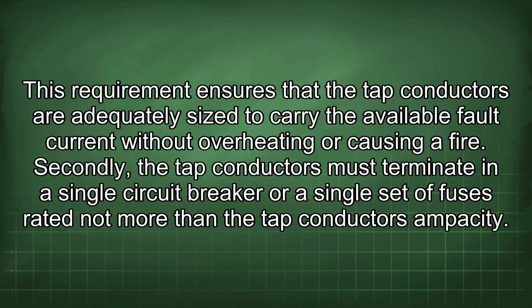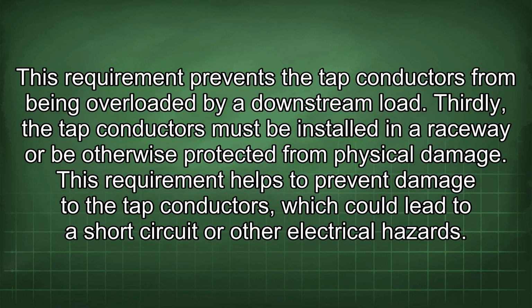This requirement ensures that the tap conductors are adequately sized to carry the available fault current without overheating or causing a fire. Secondly, the tap conductors must terminate in a single circuit breaker or a single set of fuses rated not more than the tap conductor's ampacity. This requirement prevents the tap conductors from being overloaded by a downstream load.